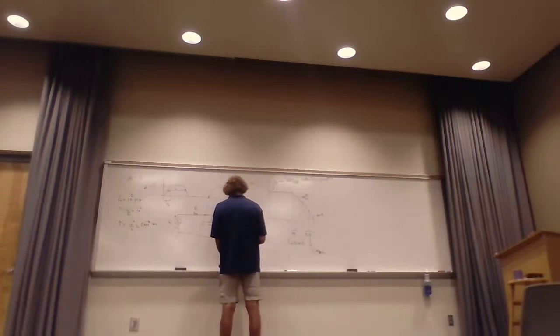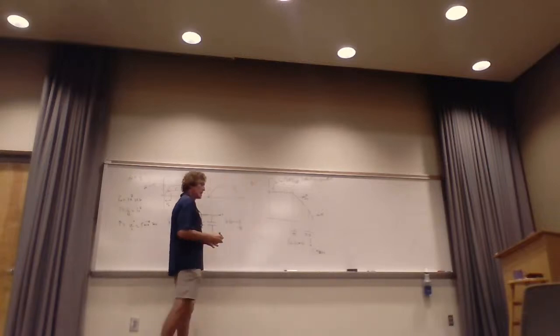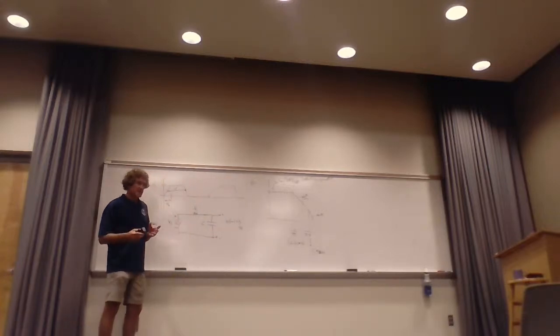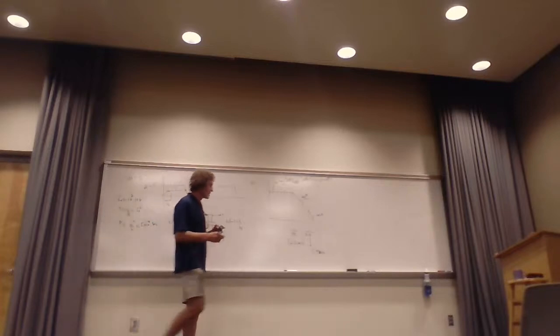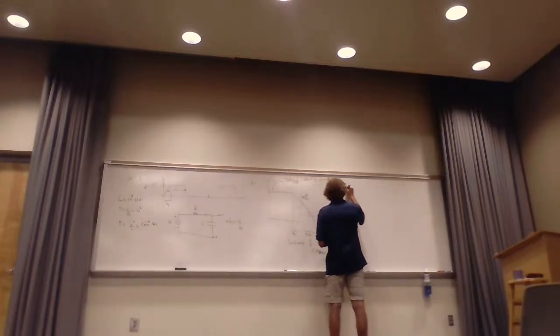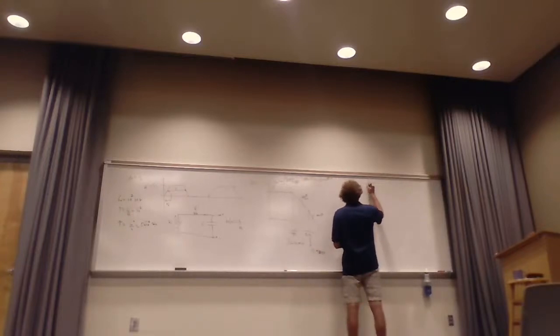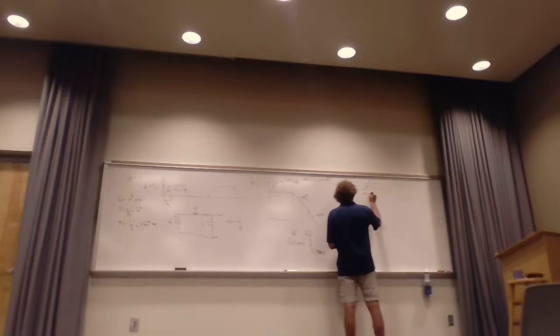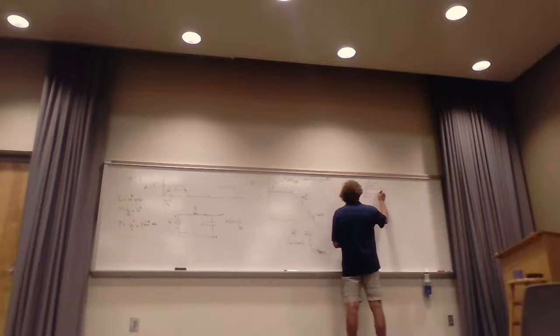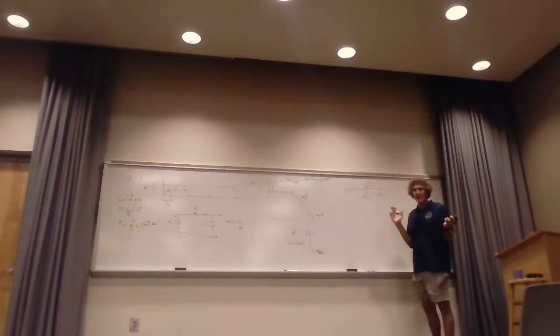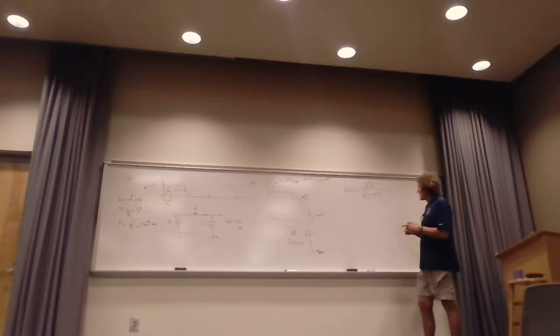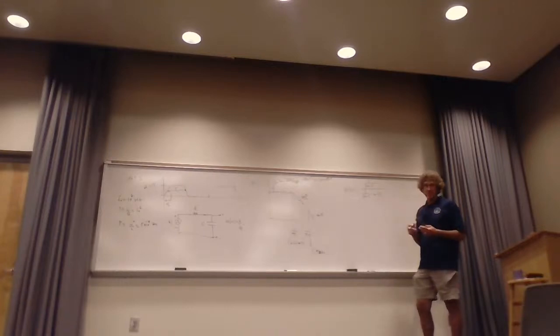Now I'm going to go ahead and do this. So if I put V out over V in here, well, if I want to just do impedances, and I think some people got thrown for a loop here. Let me do it over here. If I want to do impedances, I would say 1 over the output impedance, which is J omega C, divided by 1 over J omega C plus R. Does everybody understand where I got that? There's really no mystery here, but I've got to make sure because some people mess this up. Now, what I do, and you don't have to, but what I do is just multiply top and bottom by J omega C.